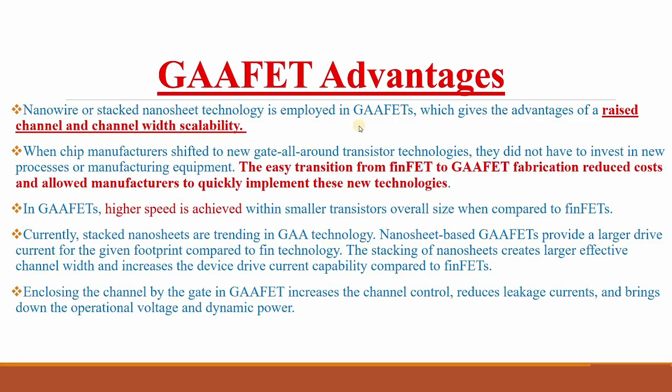We are using nanowires or nanosheets to apply GAAFET, which gives the advantage of raising the channel or channel width scalability. So we can easily transition from FinFET to GAAFET. You can use the same fabrication, reduce the manufacturing cost, and quickly implement these new technologies.